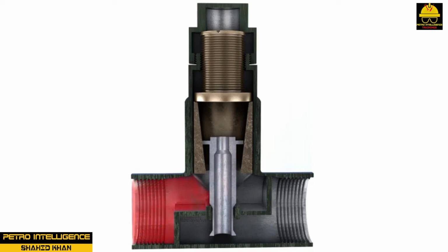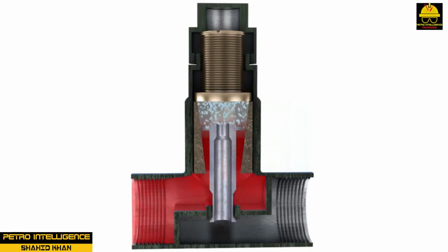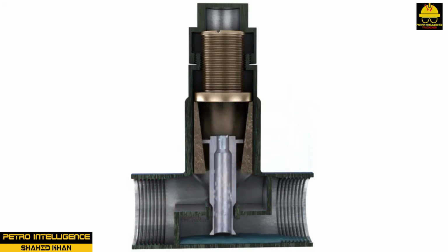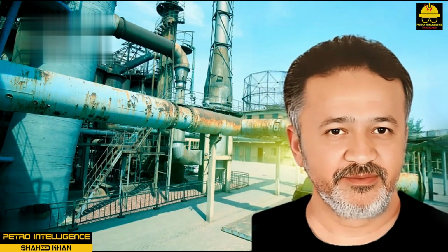Impulse traps are used on steam tracers and drip legs. They do not operate at pressures above 300 psig or below 15 psig. Impulse traps will fail to open. They are self-draining when installed in the vertical or horizontal position with the cap on the side.